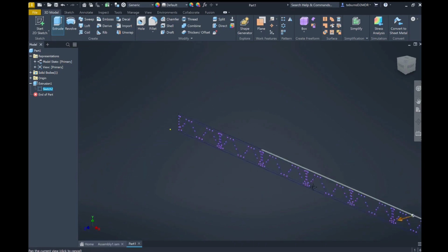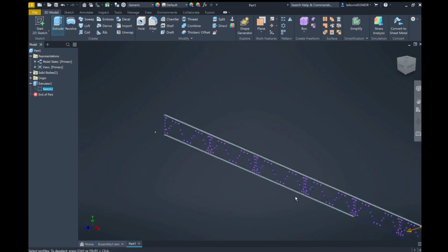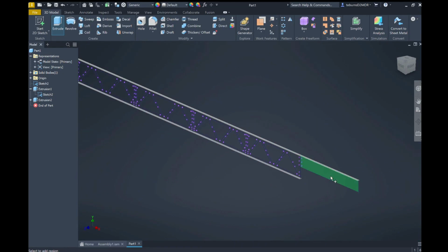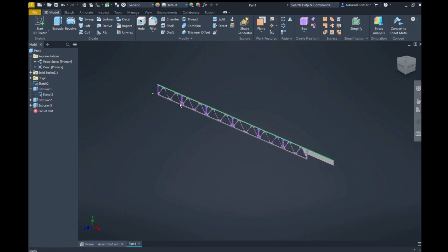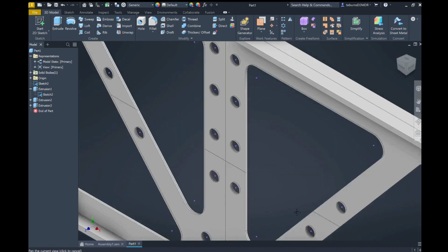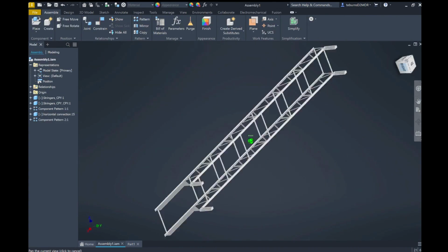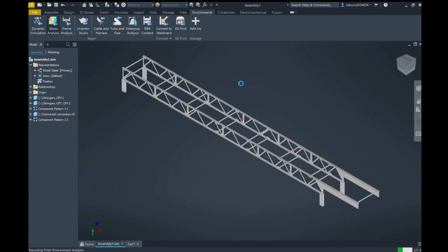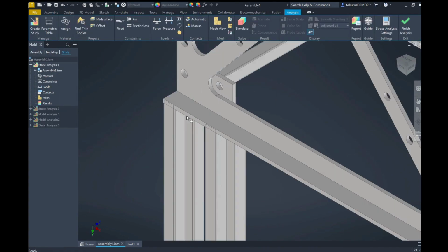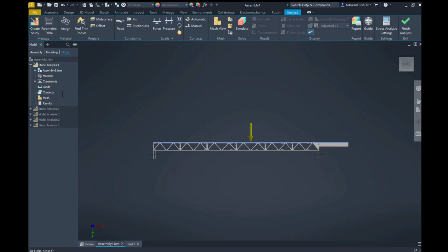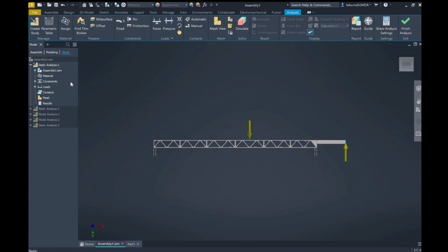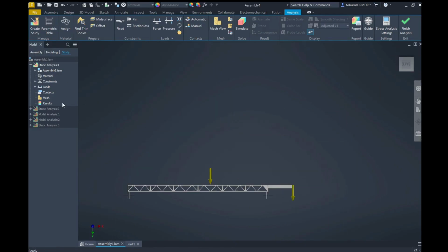We achieved this by designing stringers to use a W12x14 and scaled connections and fasteners to resemble assemblies at full size. To cut weight while keeping most of the bridge's strength, we designed a Warren-style truss cutout in the web portion of the W shape. Limit states were checked via hand calculations using the AISC Steel Construction Manual. This included stringer yielding and fracture, local torsional and flexural buckling, bolt shear, tear out, bolt bearing, and weld rupture.